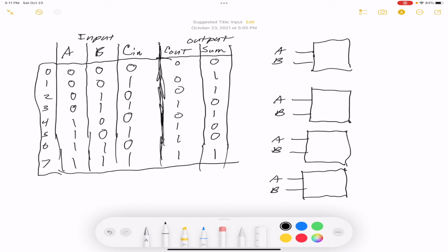Usually this here at the top will be a half adder, so there will be no carry-in bit. What happens here with a half adder, you have A and B, and you have your sum, but you have a carry out. And the carry out will be the carry in for your full adder.